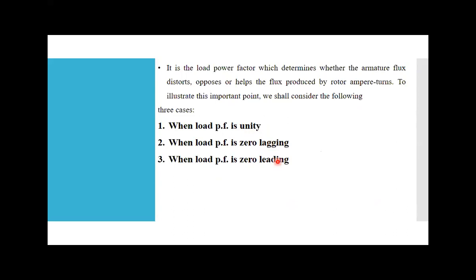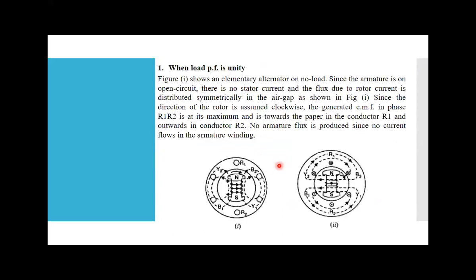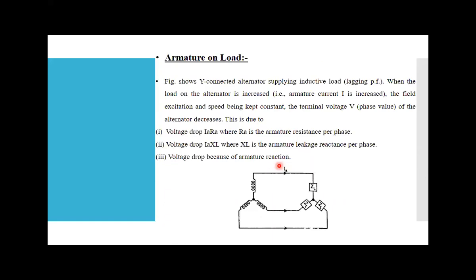Suppose your load is purely resistive, your power factor is unity. Suppose your load is purely inductive, then your power factor is lagging. Suppose your load is purely capacitive, then your power factor is leading. Here also we have the same case.